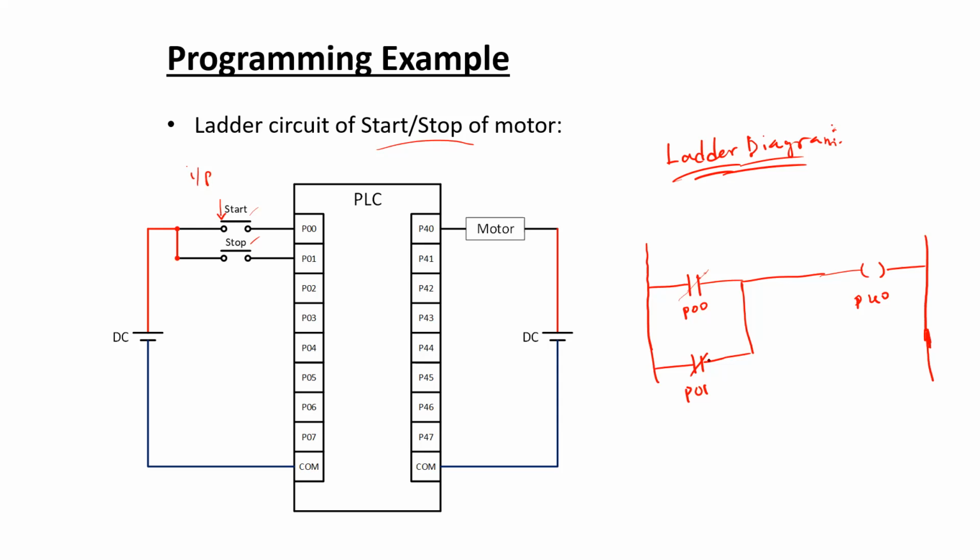Okay, no problem. You say that, but whether it would serve your purpose depends on how you connect this normally closed contact. We have to press the start button once, then the path will be closed and the power will flow, and then there will be another switch to disrupt that path. So how would you disrupt that path?